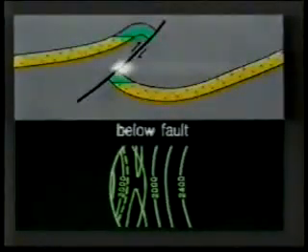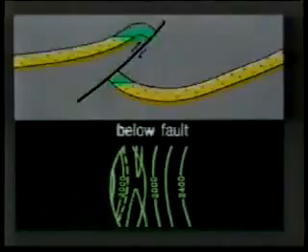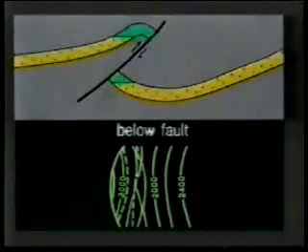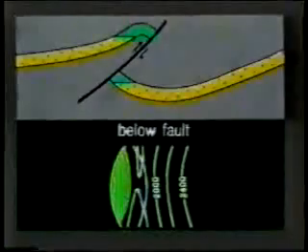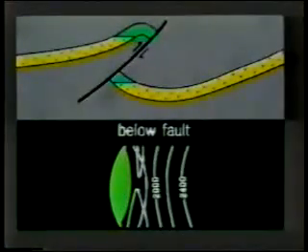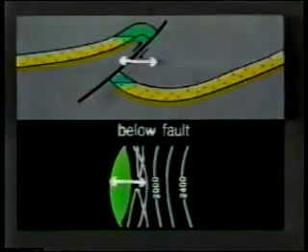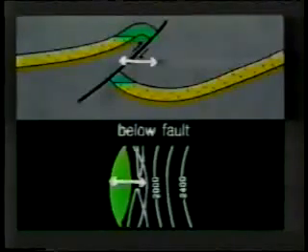Its intersection with the fault plane produces the curved lower trace. To the right of this trace, the surface is folded into a syncline, and the upturned edge of its faulted flank has accumulated oil. The distance between the lower and upper traces of the fault plane gives us the horizontal displacement of the marker horizon.